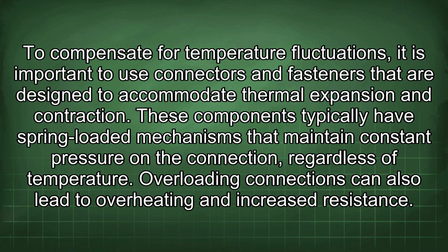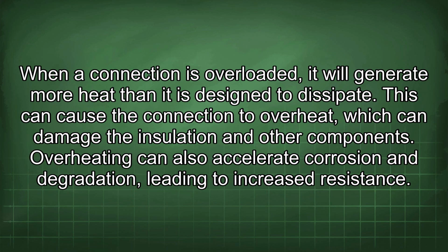Overloading connections can also lead to overheating and increased resistance. When a connection is overloaded, it will generate more heat than it is designed to dissipate. This can cause the connection to overheat, which can damage the insulation and other components. Overheating can also accelerate corrosion and degradation, leading to increased resistance.